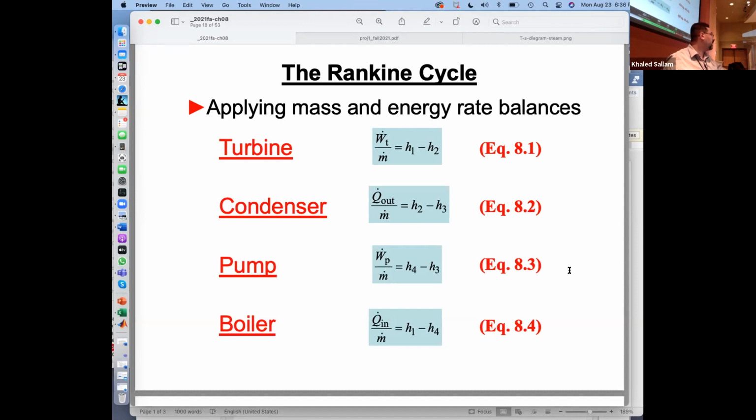And the work pump is negative. That makes sense. I buy it because I'm doing output minus input, and the equation is Q minus W equal. But if you get those negative things and you are so happy, I'm so proud that you got the first law of thermodynamics correct, and it's negative, watch out when it comes to work net. And watch out when you are trying to do the first law and say Q added is two parts, work net and Q rejected. Very good. Questions so far?